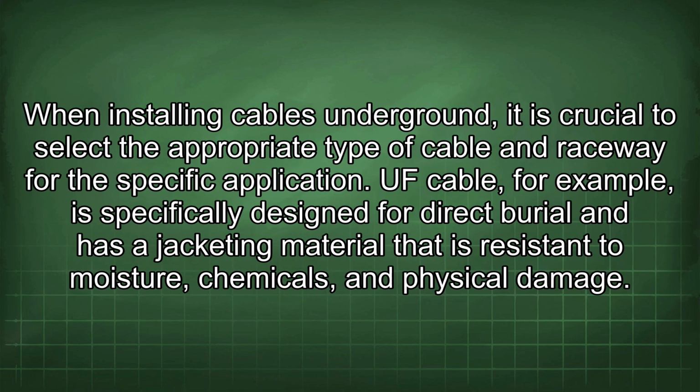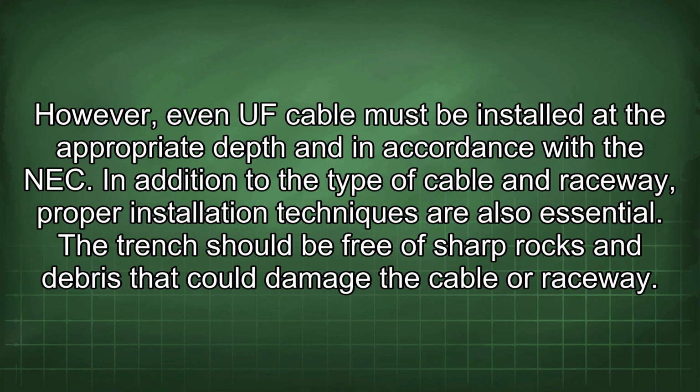damage. When installing cables underground, it is crucial to select the appropriate type of cable and raceway for the specific application. UF cable, for example, is specifically designed for direct burial and has a jacketing material that is resistant to moisture, chemicals, and physical damage. However, even UF cable must be installed at the appropriate depth and in accordance with the NEC.